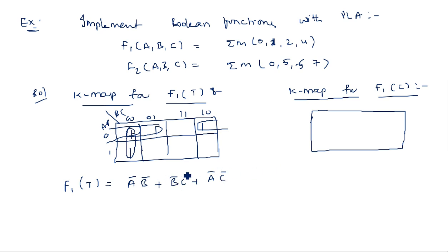So if you take the complement, you need to apply Boolean algebra laws like De Morgan's law, commutative law. So such laws you need to apply and derive. That is one way. Otherwise, you can take the help of K-map and simplify it. When you are going for the complement, the mapping should be with zeros, not with ones.